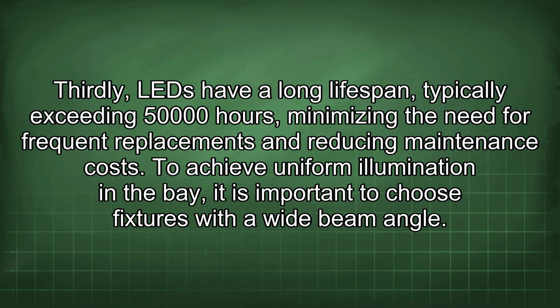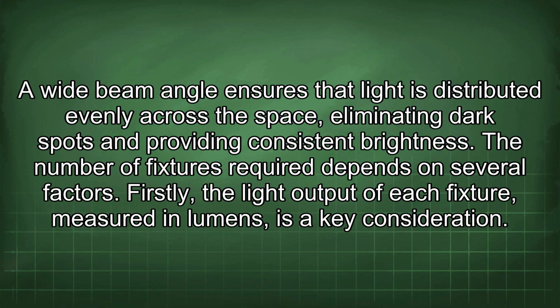To achieve uniform illumination in the bay, it is important to choose fixtures with a wide beam angle. A wide beam angle ensures that light is distributed evenly across the space, eliminating dark spots and providing consistent brightness. The number of fixtures required depends on several factors.